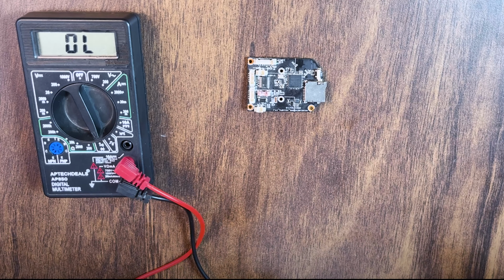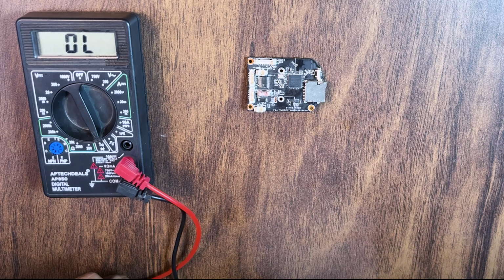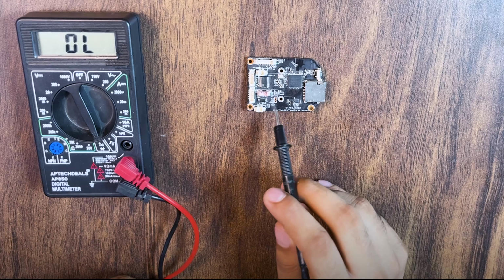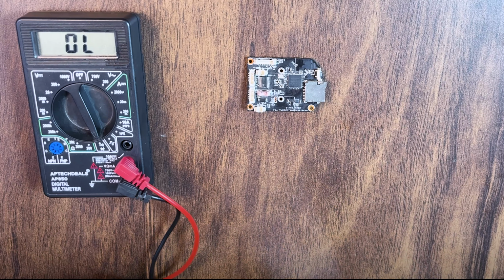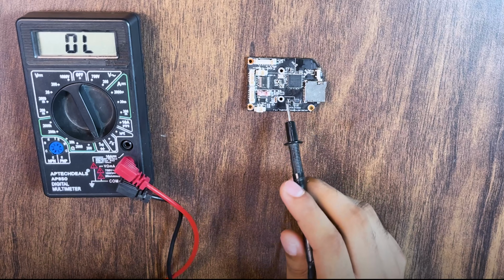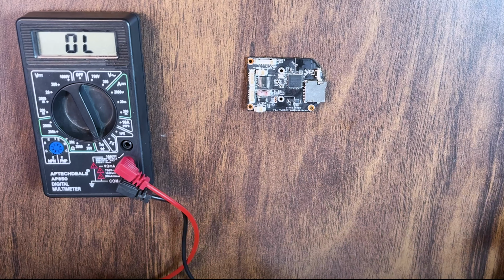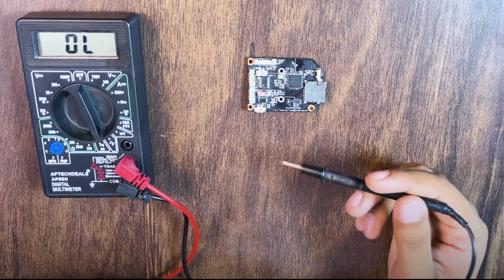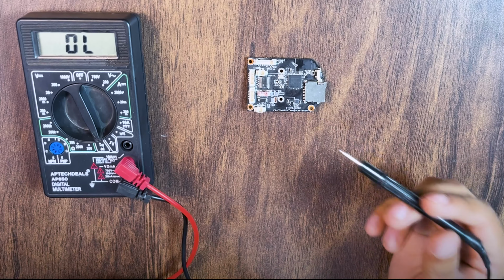Whenever this actually comes in real life where you won't have the UART listed, you will go through each port one by one, and there will only be one port out of the 3 or 4 ports which would give you continuity with a reference ground. Now, one thing that you might note is that there's no VCC over here, and I said 3 or 4 ports. Well, a lot of the times the VCC is the power being supplied to the motherboard using the external power source. So they might not actually provide VCC through the UART ports.